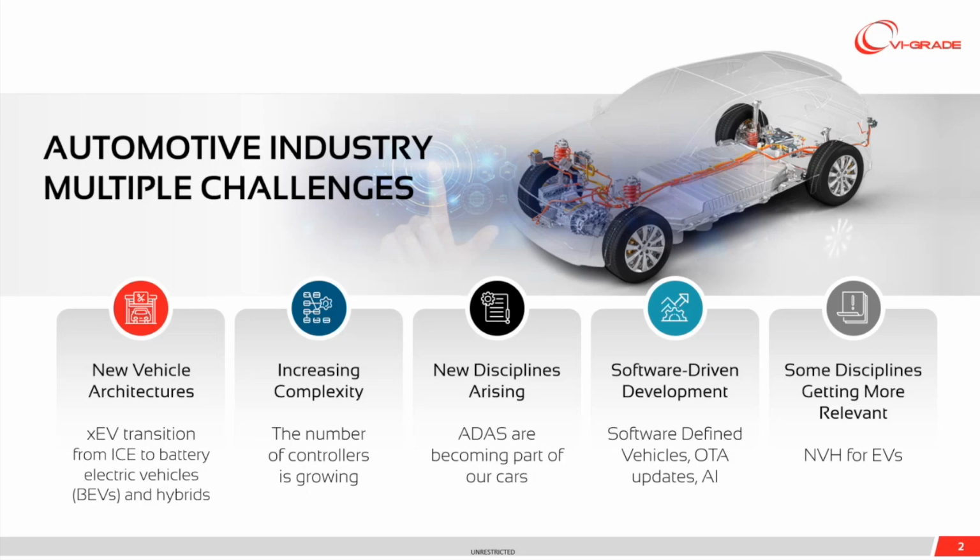And finally, some disciplines related to the transition from combustion engines to battery electric vehicles and hybrid vehicles are reshaping some expectations and also some development priorities. As a consequence, NVH is becoming particularly important for electric vehicles, where the absence of engine noise is exposing other phenomena, which are therefore becoming more and more of a challenge to manage.